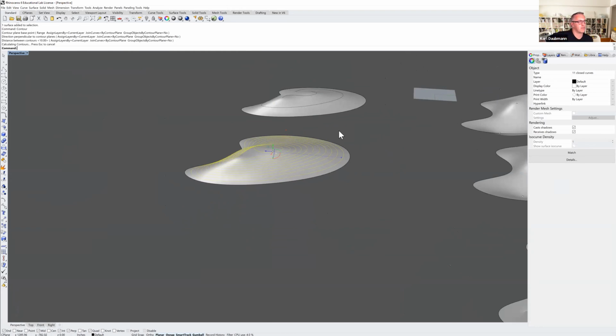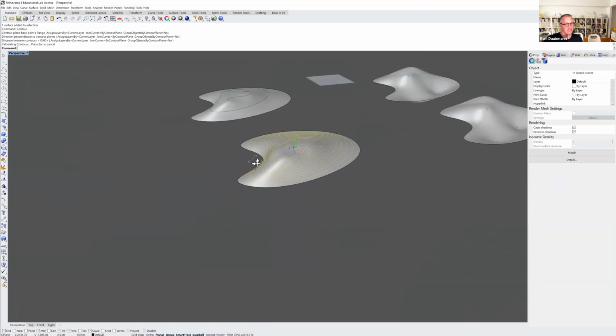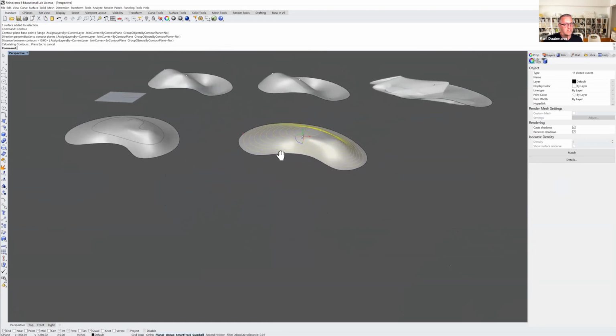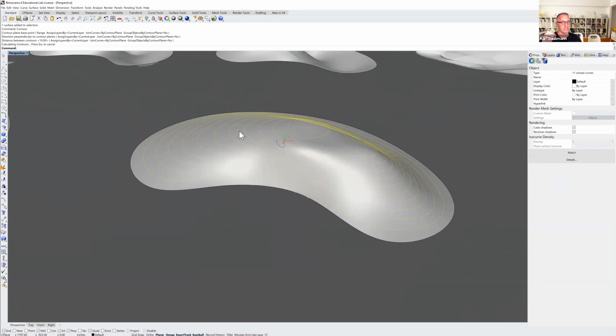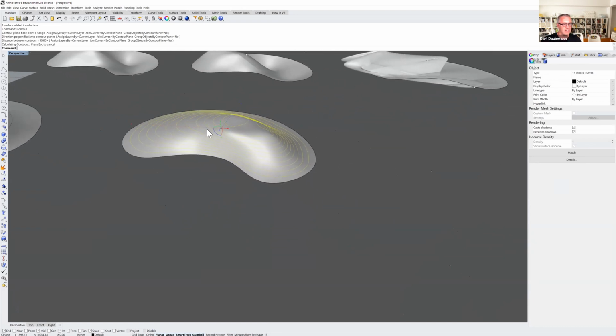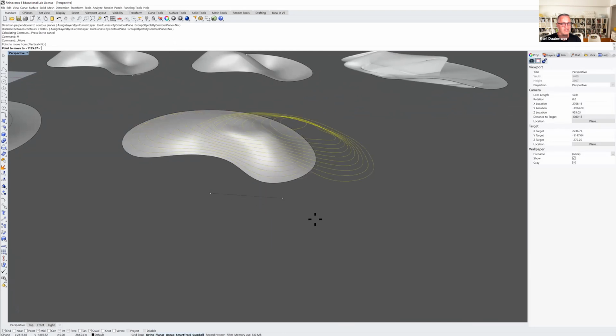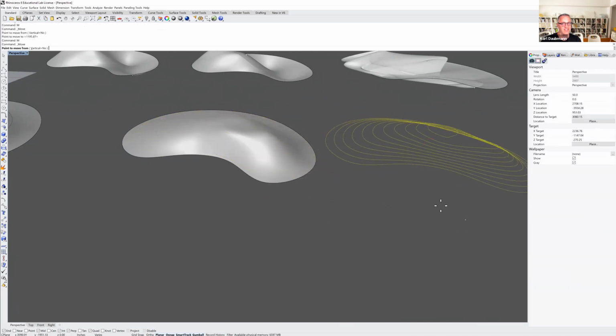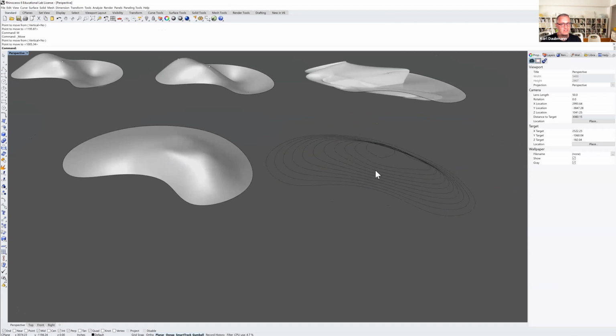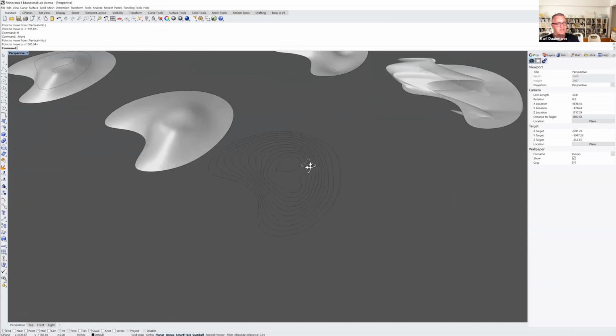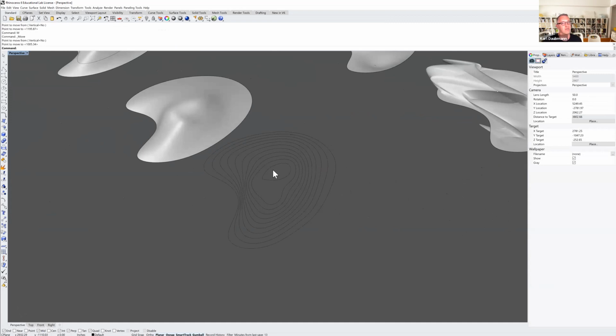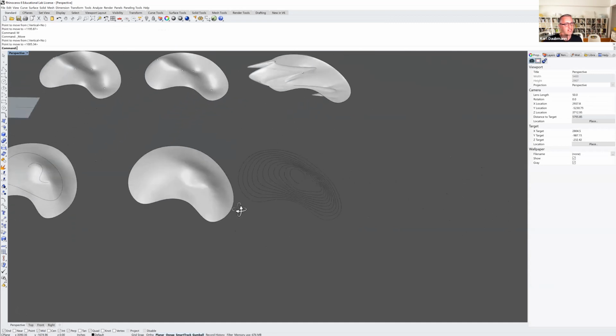Did everyone get a patch surface to work? It's basically just like a big piece of rubber stretched between whatever geometry you give it, which can be good and can be bad. It's as precise as the inputs that you give it. And so I've often worked iteratively, like, okay, I might take it and contour something and then use those contours and maybe adjust the contours and then repatch the surface, or just keep working on something as a way to get something to be where I needed it to be.